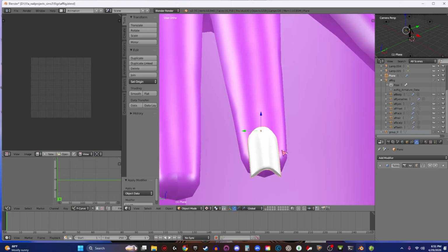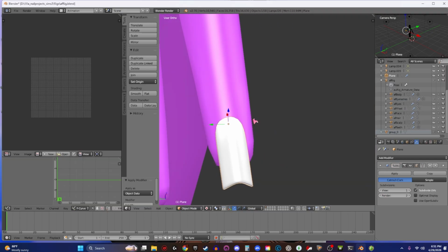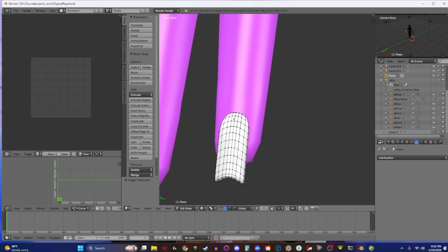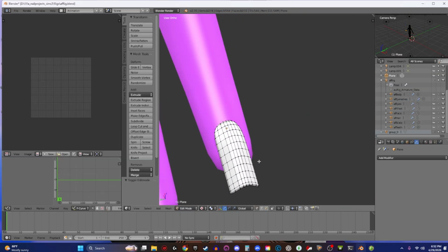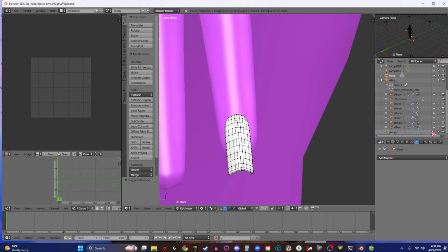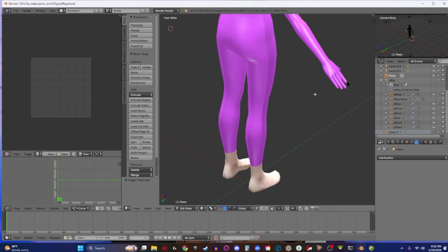And then we're going to apply the subdivide modifier. Make sure that it's on 1 because this is what's going to cut extra vertices. That's what made the shaping look like this. And once you apply it, we're going to go into edit mode and you're going to see the vertices here. Now that we've done that, we already have our reference mesh turned off.